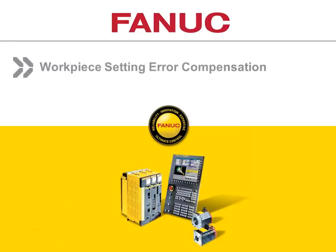So the first thing we want to talk about, and again, this is just sort of a sequence of events in a program, is workpiece setting error compensation, because with that, we're telling it where the part is. We're letting the control know where it's located. Because when you do 5-axis machining, and I'm an old machine operator, at some point with 5-axis, you've got to get a hold of the part. You have to have some sort of work holding where you can clamp onto the part. This isn't like a 3-axis machine where you're going to throw this part up in a vise, because you're going to run into interference zones.